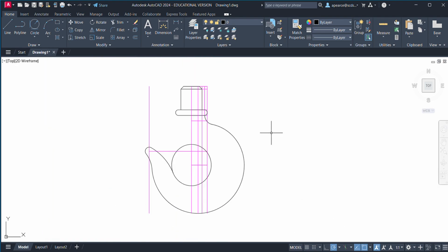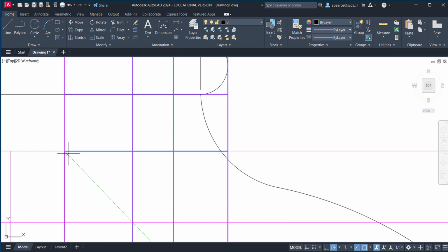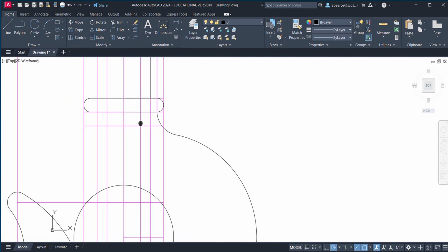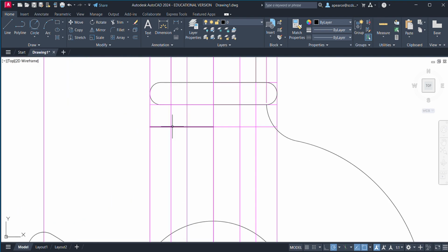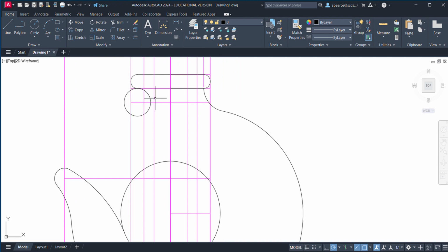Now we still have to do the front side of our hook, and that can be done a couple of different ways. The first thing I'm going to do is go to mirror, and flip these lines through the middle point so they appear on either side. And we're going to start with a circle with a radius of 4. So if I go here, there's my radius of 4. I'm going to move this circle in 2 units, and that gives us a good location for this bottom part coming down, and our curve or radius still being the correct one of 4.